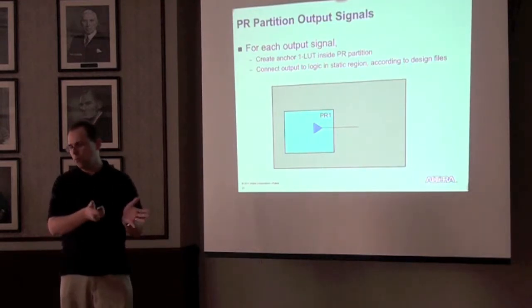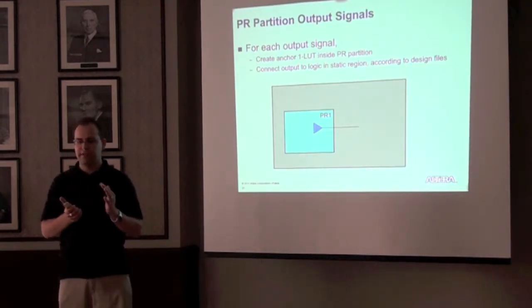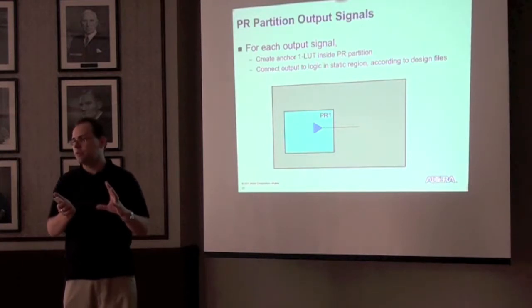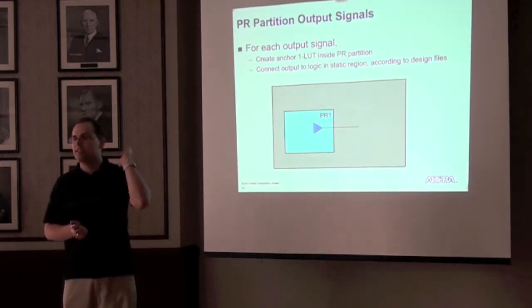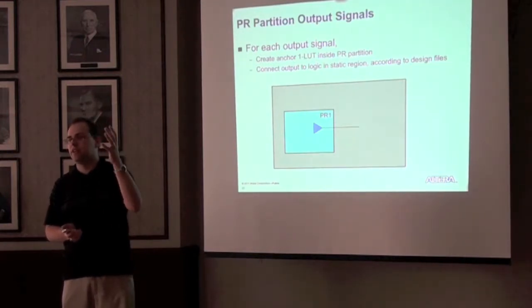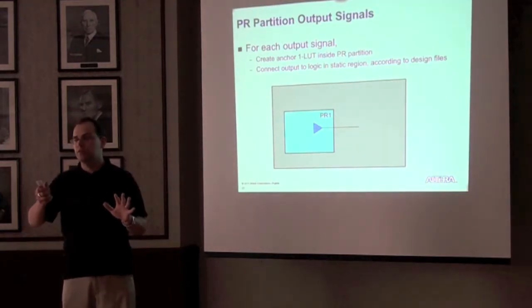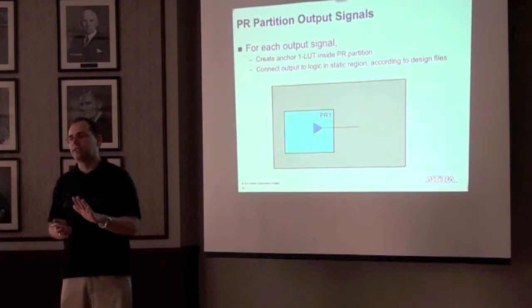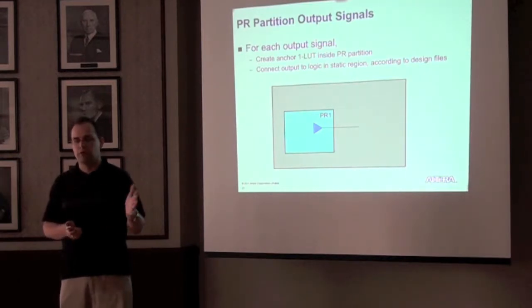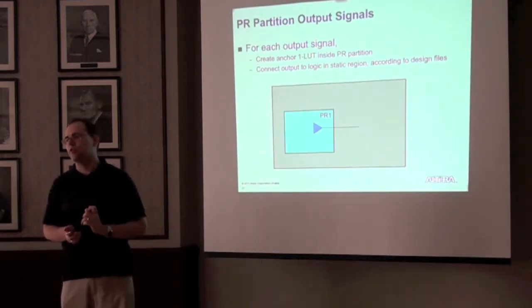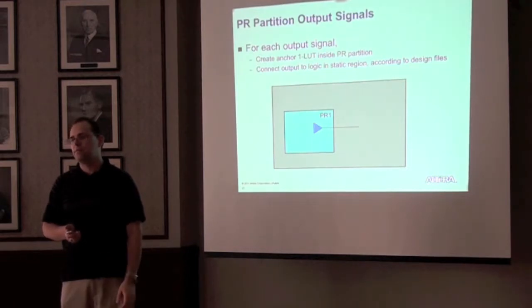So the way that a user knows that the design is ready, or the PR partition is ready, is that there's a signal coming from that control block saying this is ready. So it's expected that that signal is wired up to the rest of the circuitry to declare that it's done. One cannot assume that the order of the LUTs is in a particular order. So internal to the PR region, you can't generate a self-timed signal that says I'm now fully active. That's correct.